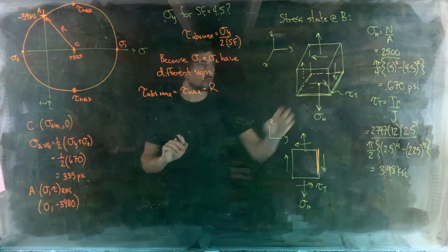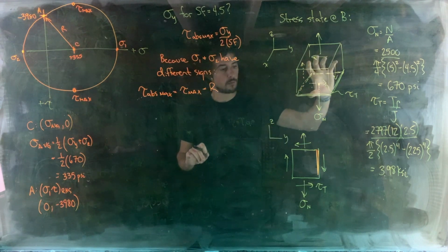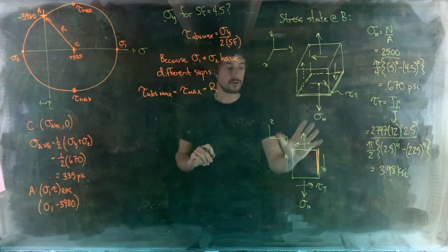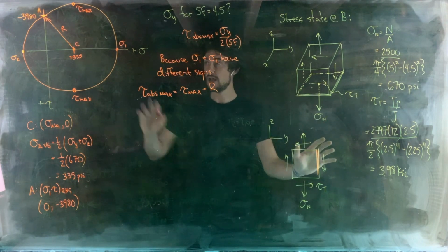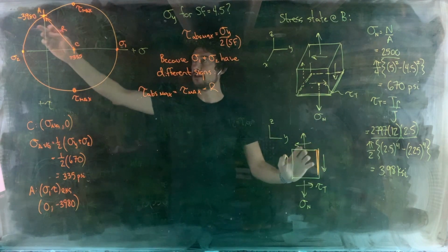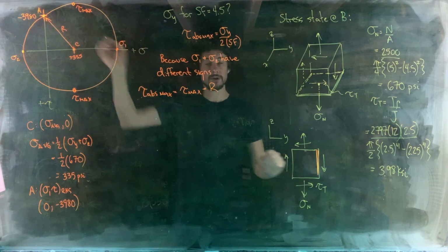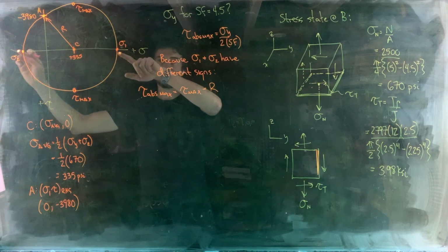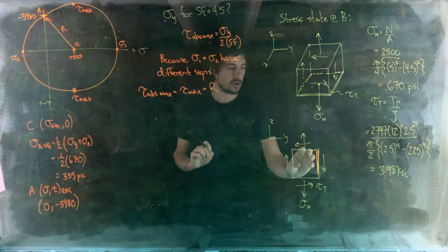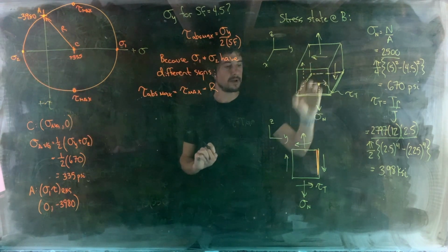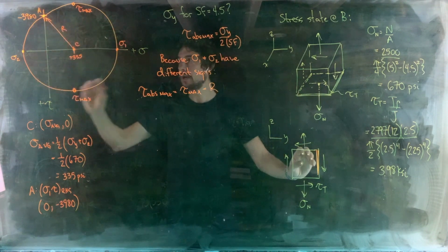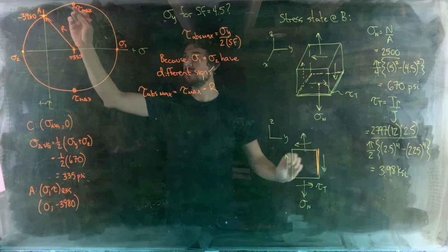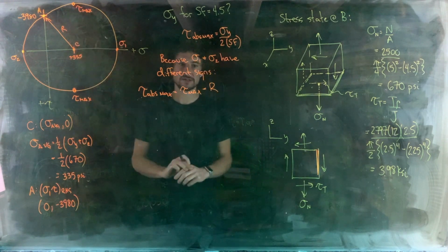When you draw your volumetric element from one of the other viewpoints, one of the other in-plane representations, and you draw Mohr's circle based on that, you actually end up with a larger circle. For differing principal stresses, it doesn't matter which in-plane element you draw. The in-plane element that we've drawn here will be the largest circle that you get. So this is the absolute maximum shear stress.